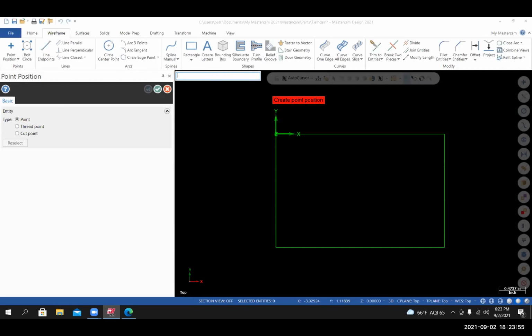You can type in 0.375, comma, separate the values with the comma, negative 0.375. And it's understood x, comma, y, comma, z. So x is 0.375, y is negative 0.375. And if you omit the z in this particular case, it's just understood to be 0.